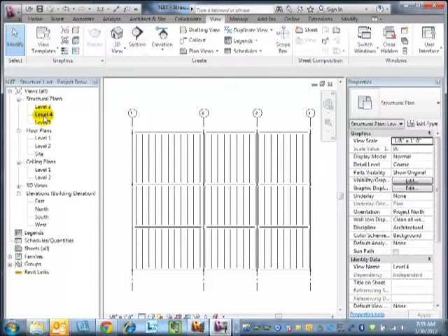So rule of thumb, be careful with your copying. Or try to avoid all of that. It's one of those holes that'll get you into trouble, because copy and paste doesn't carry all the constraints. It carries the location, but not the constraint. That might be the easiest way to think about that.